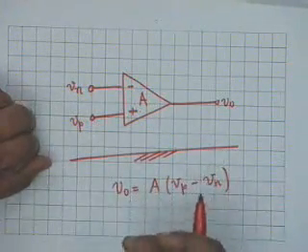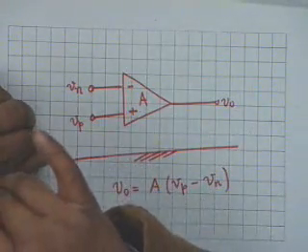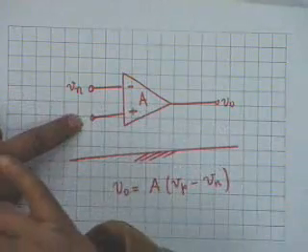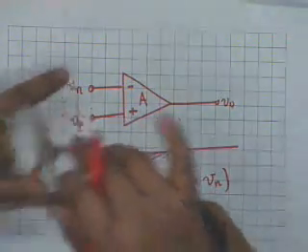For example, if you have 1 millivolt and you want a plus 1 volt out of it, then you can apply it to the non-inverting terminal. On the other hand, you might require a minus 1 volt, then you apply the input to the inverting terminal. All right, so it is a more versatile amplifier chip than the conventional amplifier, where there is only one input and one output. There are two inputs here which can change the sign of the given input voltage.